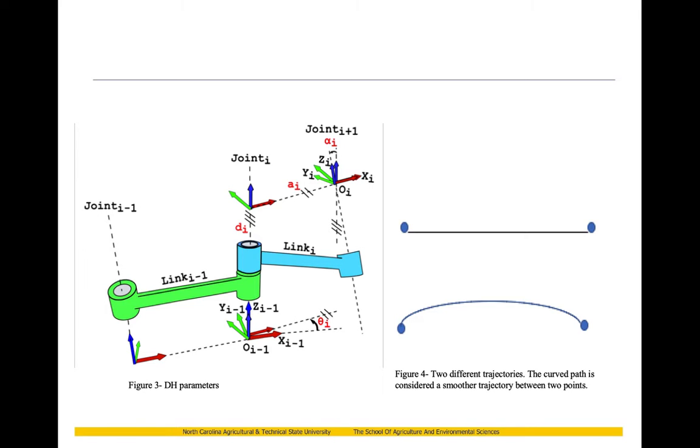As the arm moves, the sudden changes from waypoint to waypoint can cause instability in the system. To create a smooth path, a parametric curve between the points is used rather than a linear path, outlined in Figure 4.